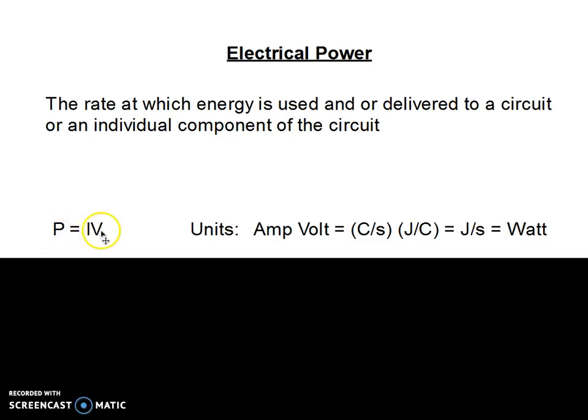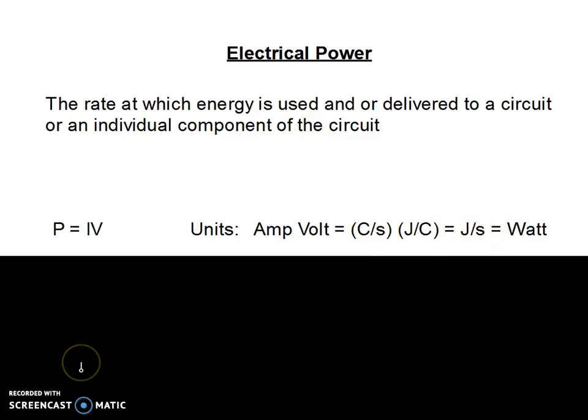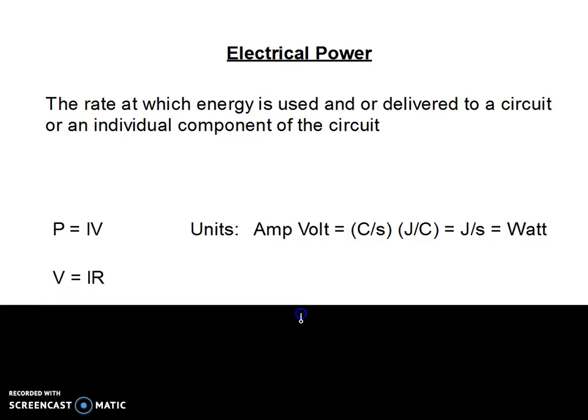So just using this simple equation, you can determine how much current flows through that 60-watt bulb. And again, the 60 watts means that that light bulb, when it is on, uses 60 joules of energy every second.